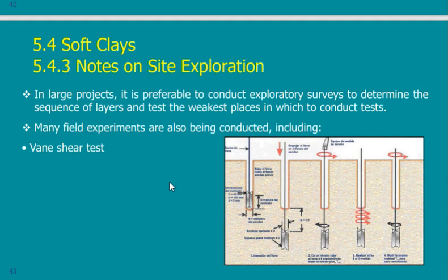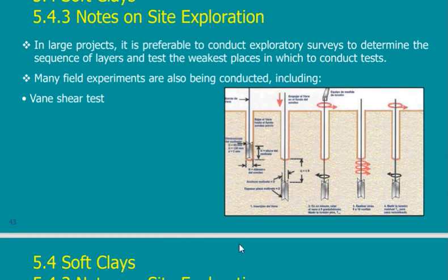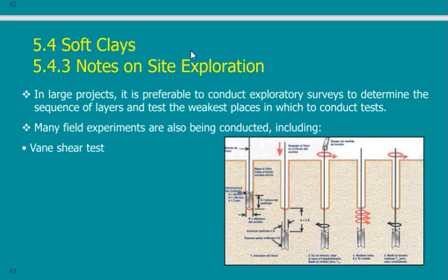on-site testing. So what type of on-site testing? We said that we have something called the shear vane test. This test uses a vane, a double blade with blades perpendicular to each other, which is immersed inside the soil.